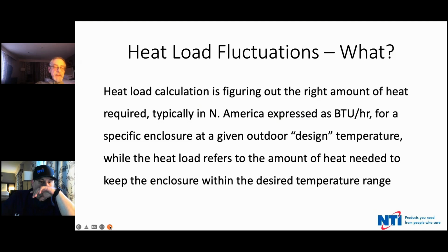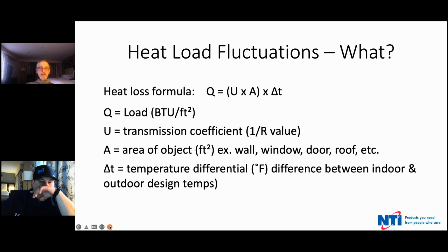And here's how that works. Honestly, these days pretty much everybody does a computer-aided heat loss if they're doing one at all. And God, I hope you all are doing it one way or another. Yes, please. But so you understand the math behind it, it's really not difficult. It's that universal heat formula where Q is the load in BTUs per hour. U is a transmission coefficient, which is simply the inverse of R. So if you know the R value, it's just 1 divided by the R value is how you get to